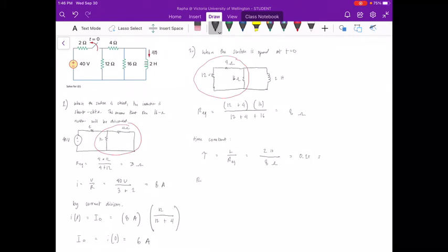So therefore, our final step is to solve for what the formula of i(t) will look like. We have i(t) is equal to I sub 0 e to the power of negative Rt over L, or I sub 0 e to the power of negative t over tau.